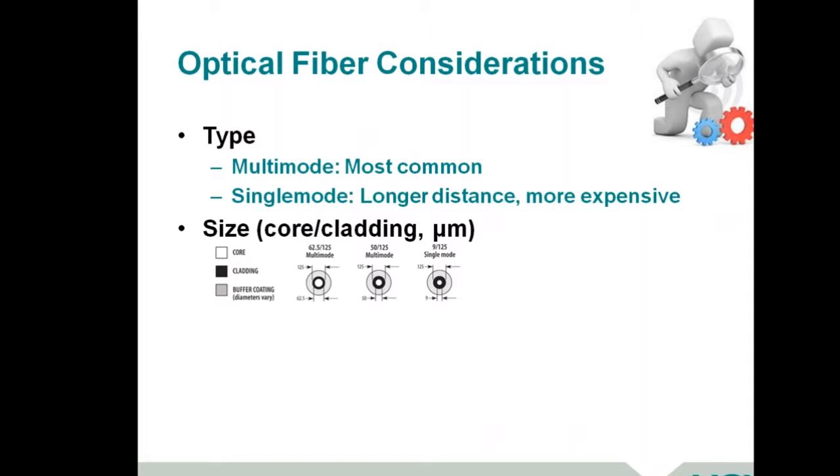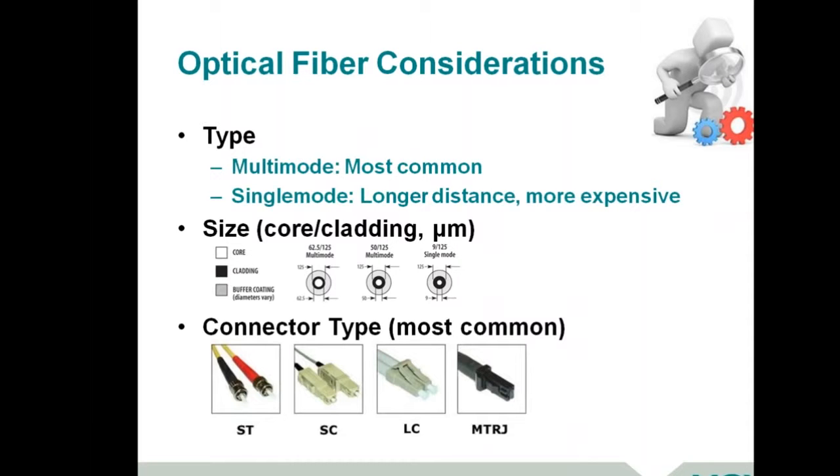That's important in the selection process, and I wouldn't get too concerned about this, since most folks will be bringing in a specialist to do this type of thing, since you do need to terminate cables. Maybe more pertinent to most of you joining us today is choosing patch cables at the edge of your network. And then lastly, the connector type. This is where it gets a little complex, and particularly in choosing the type of media converter you want to use, you need to match the terminations of the fiber to the terminations of the equipment.